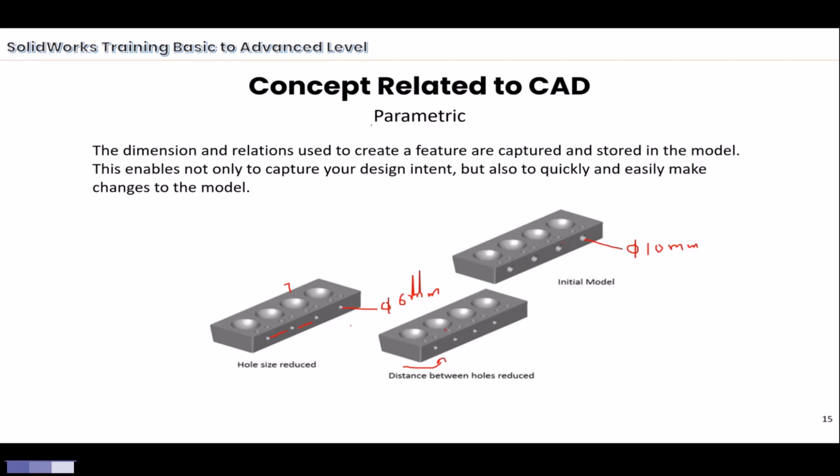So the same concept is called parametric modeling. You have heard this word so many times, parametric modeling. These software are parametric modeling software. Why do we call it parametric modeling? Because we can make changes by editing the dimensions anytime, and those changes will be updated properly. When we make a part properly following a design intent, relations and dimensions, that is possible.